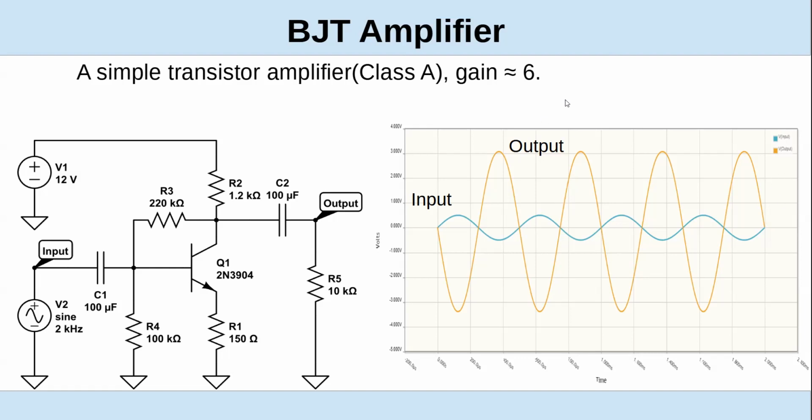That's one of the advantages, and that's why you'll see Class A amplifiers in a transmitter for the audio section, for instance, before a speech compressor. So distortion typically either shows up as ripple or clipping. And I have the thing to talk about the effect of clipping coming up.